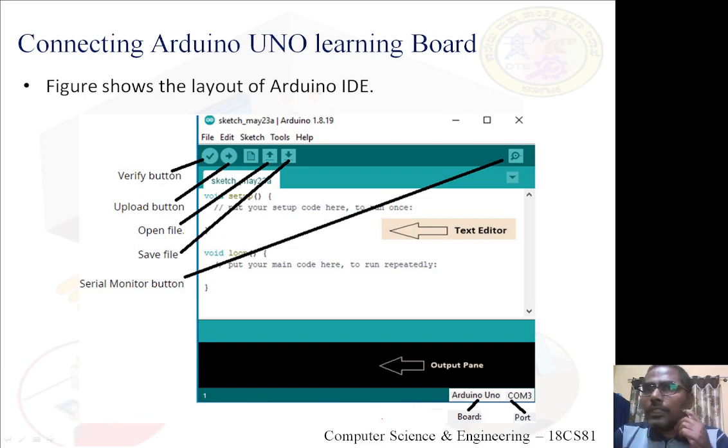And there are one or more serial ports available on your computer. So to which serial port have you connected Arduino Uno? That is shown as COM3 in this case. COM3 is the serial port to which Arduino Uno is connected. Before that, after loading an IDE and before writing code, we need to follow two more steps. Let me come back to that.